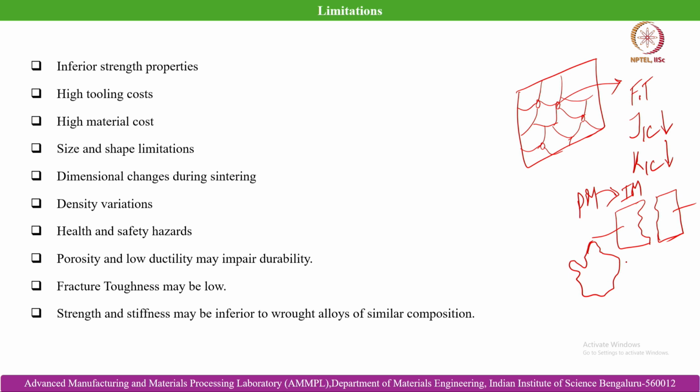Generally we make the dies with hardened die steel, so their machining becomes a challenge and also expensive, whereas in cast or formed parts where we leave room for machining, the materials are often easy to machine, like light metals and others, and you can machine them at a much lesser cost and machining time.